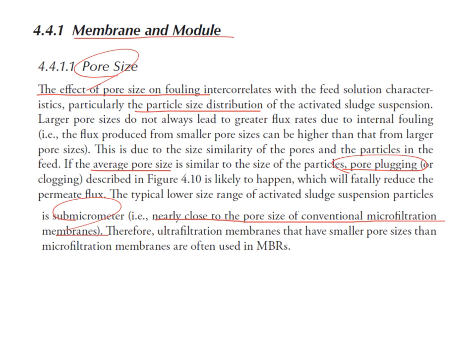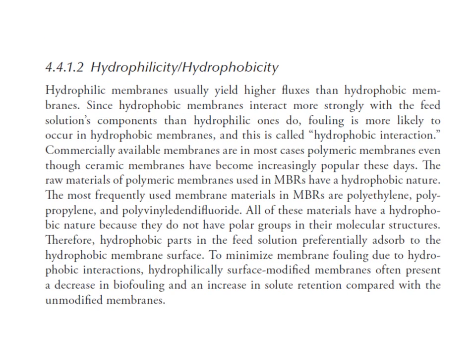So ultrafiltration, which has a smaller pore size, is sometimes better than microfiltration because it can prevent plugging by these submicron particles.